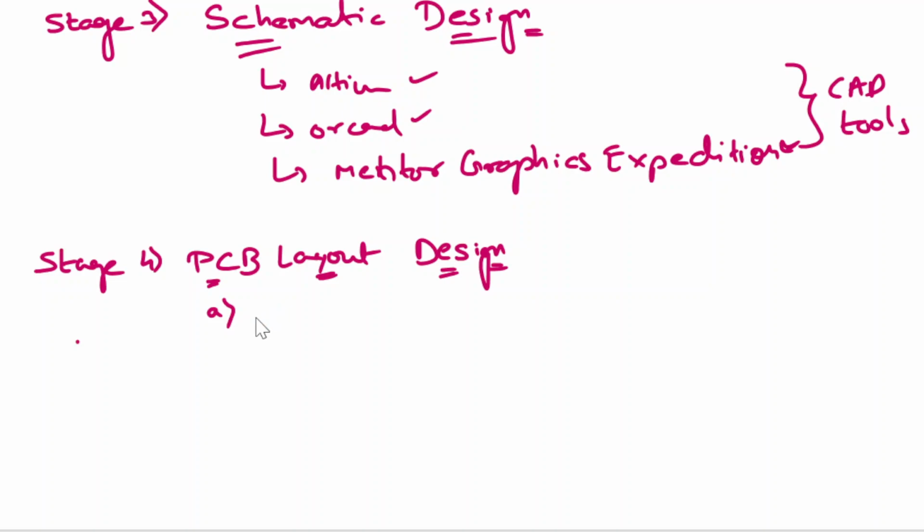See, the reason we need to talk to the manufacturer is that there are certain materials specifically used for such high-speed requirements to match, and there are certain trace widths as well as thicknesses of the copper foil. All those things are required to attain the required characteristic impedance. So if you do something in your CAD tool and ultimately the manufacturer says, sorry boss, we do not support such board thickness, such dielectric material we cannot use, we don't have that availability, that will create problems, right?